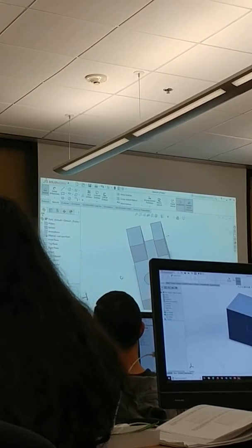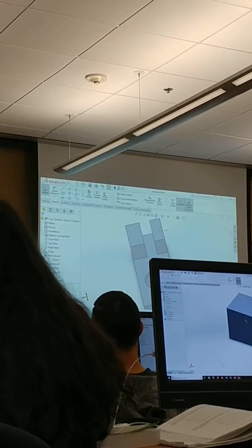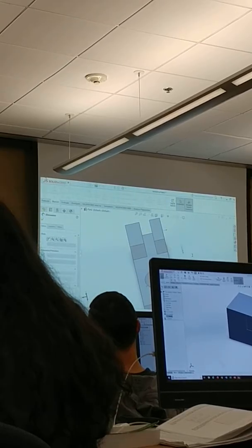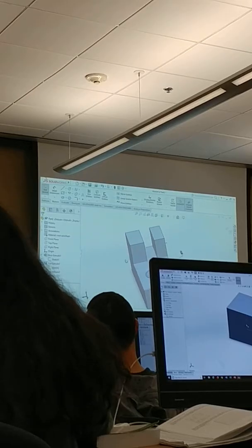It's still blue. So what I'm going to do is I'm going to take this smart dimension, I'm going to click the outside. The outside, and look, it does the standard way of drawing. So it gives me the diameter, we'll call it 5. But I still need to determine where that circle has to be.